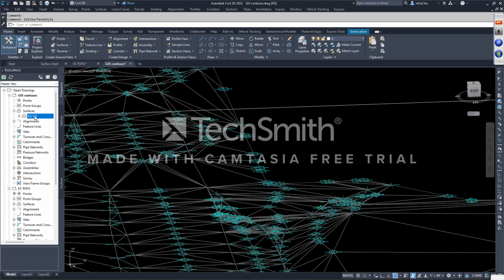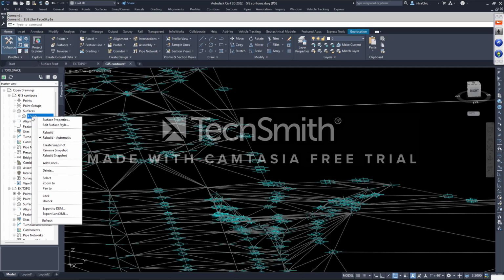I can get to it through the tool space by selecting the surface, right-clicking, and I have options for rebuilding, meaning I made a change, I need to force a rebuild. I could leave it to rebuild automatic. Every change I make automatically updates the surface. It's annoying at times. This works great for an existing surface. This does not work great for a final design surface. I can make a quick snapshot, take out a snapshot, rebuild the snapshot I made because I made enough changes that the snapshot's now out of date.